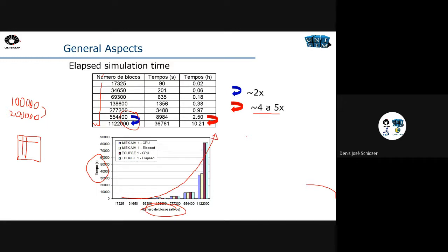Why? Because computers have limitations in memory. We don't have one equation per block, but normally 3 or even more. The convergence is worse. When the blocks are smaller, the time steps decrease. The problems in convergence increase when you have smaller blocks and so on. Of course, the results from this to this are much better, but the simulation time also increases very rapidly. Okay.